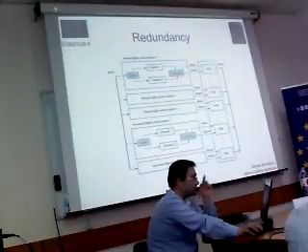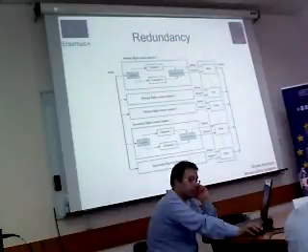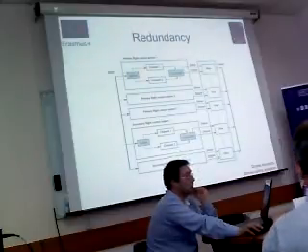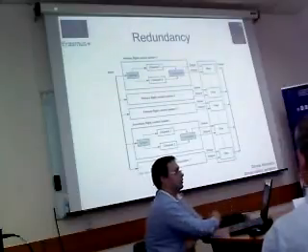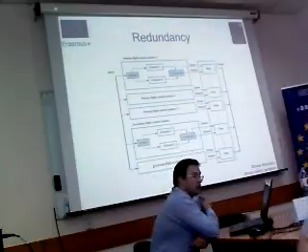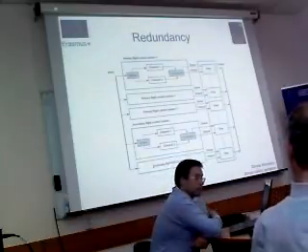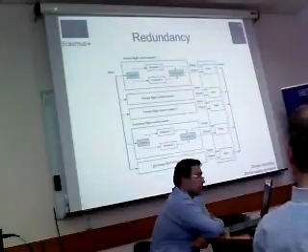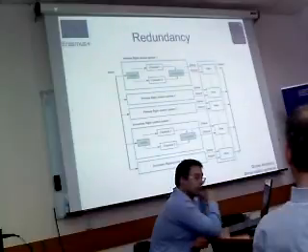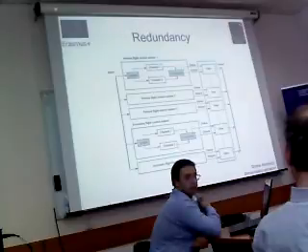So this is an Airbus flight control system diagram. Only the first system of which is expanded. So the boxes for systems 2 and 3 look the same. Inside, input is from the side sticks and output goes to the hydraulic valves of the control surface. So the coding happens first in the comparison step between the two channels and again in the filter between the single systems.